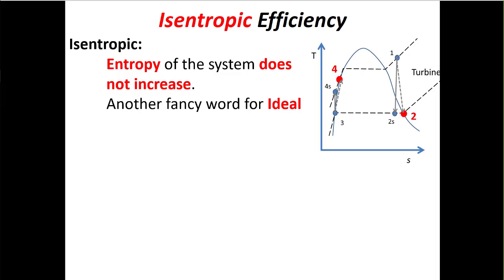What's the word where you have to, I'm in engineering, not in English. I think that's, two words mean the same thing, right? It's not exactly the same as that because isentropic really specifically means that the change in entropy is 0. But we only ever talk about isentropic processes when it also means that it's ideal, right?